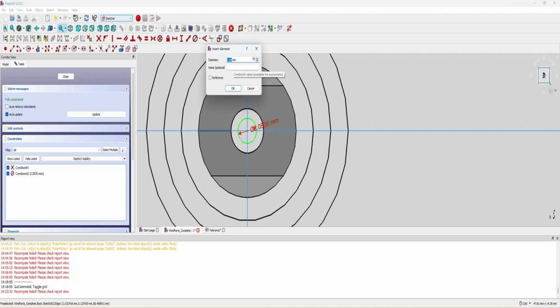constraints. And then in this case, I also have to use the formula as before so that I can add my additional tolerance from the 3D printer onto this. So here I add the inside diameter tolerance, and I don't have to divide by 2 because this is already a diameter constraint. So I save a little bit of time with that.